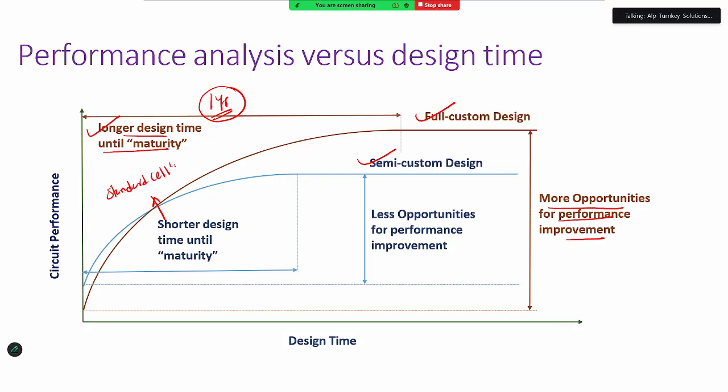standard cells, which are nothing but, suppose in digital we already saw some adders, gates and flip-flops, counters. Those are pre-designed, and they will take and use those. Here, full custom design means they will make their ICs from scratch. Semi custom means they will take some standard cells and implement them in their design.